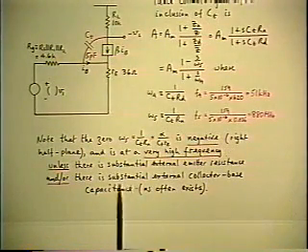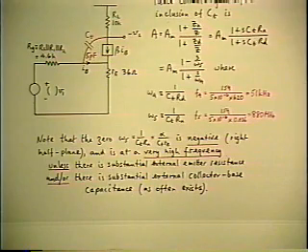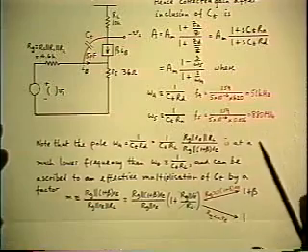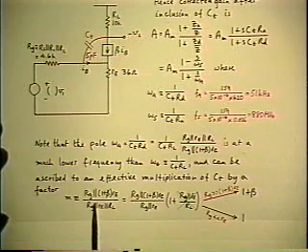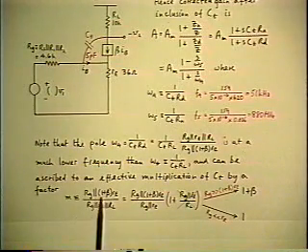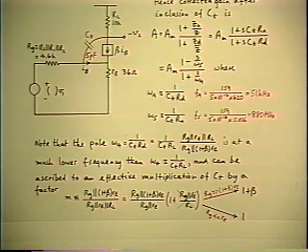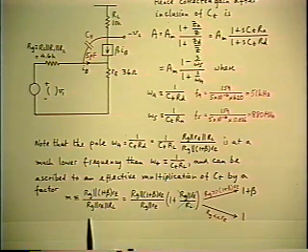Okay, this is disposing of the right half plane zero, and this is looking at the pole now. I'll give a symbol to that multiplier. Obviously M is a good symbol because it stands for multiplier, and it also stands for Miller, so that makes it very nice.